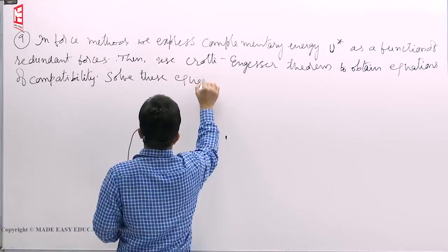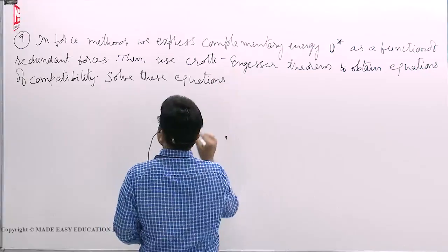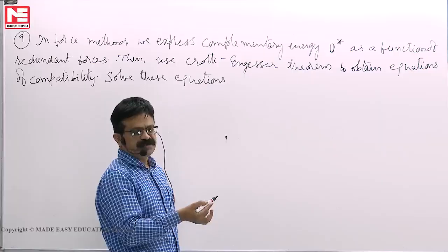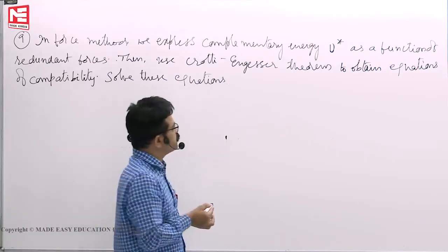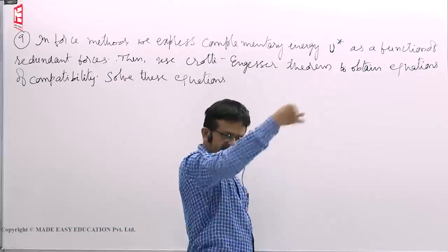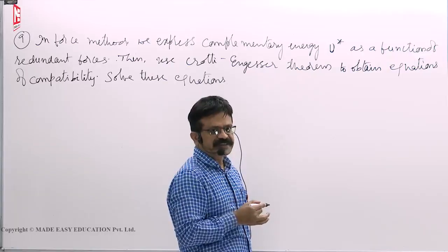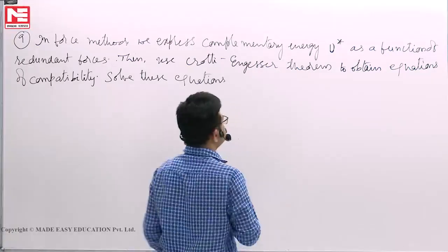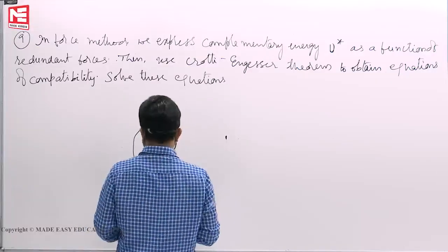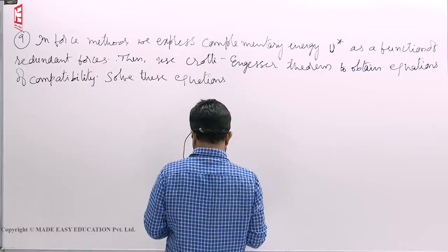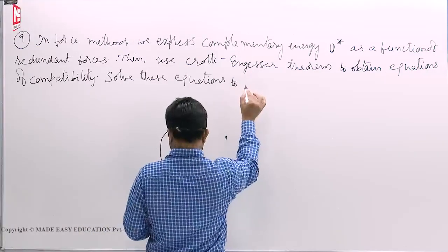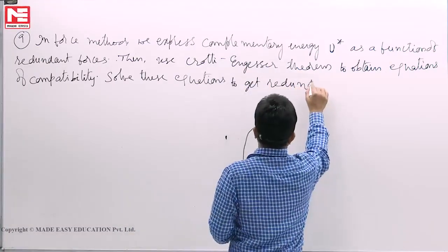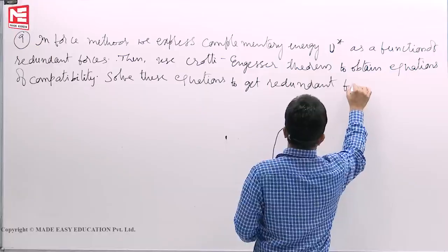Solve these equations, the compatibility equations. How to solve them, we see the examples in the flexibility matrix method. We express them in a systematic manner in the matrix methods. There I will write a set of compatibility conditions, equations of compatibility. Solve these equations to get the redundant forces.